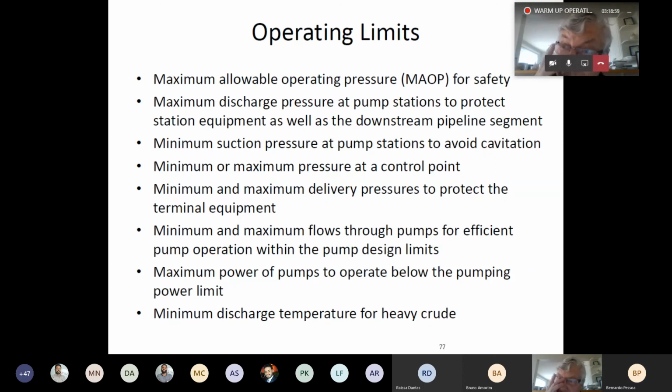If you do have a problem with, say, overpressure, sometimes you might find the pipeline might surge. Then you can have bursting discs. Although if they burst, they're a bit of a pain to try to replace them. So what people are inclined to do now is they use what are called surge chambers, and so they're surge tanks. So as the pressure would increase, suppose a valve were to close suddenly downstream, or a pump was to come off, maybe a lightning storm or something cut off power, and the pump could no longer pump, you would get a pressure wave going up, and it would increase the pressure.